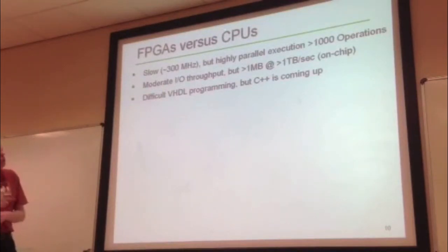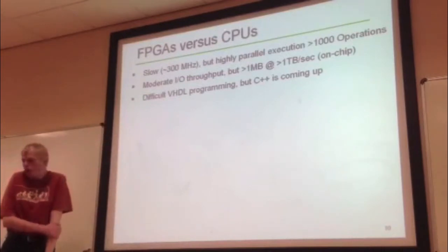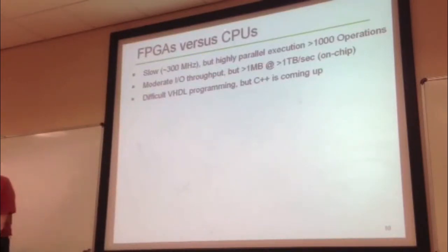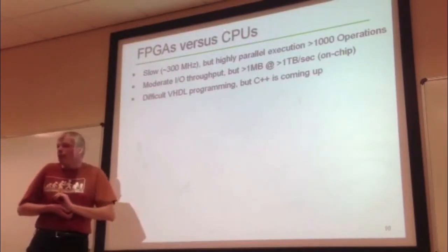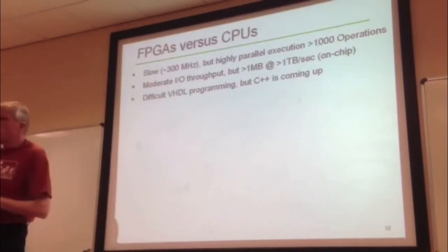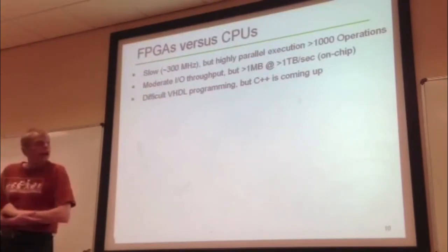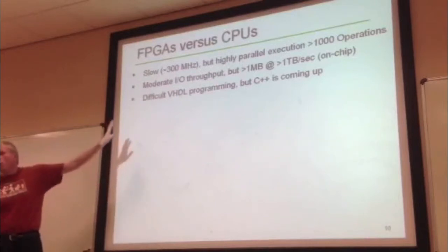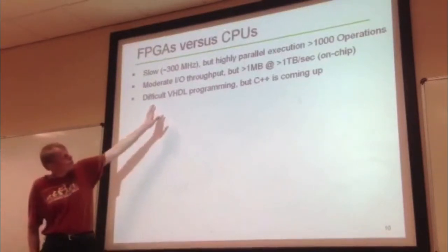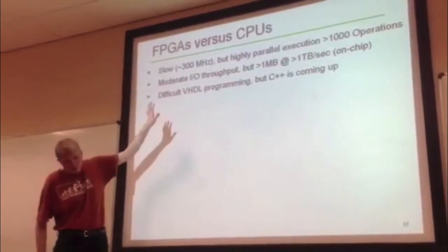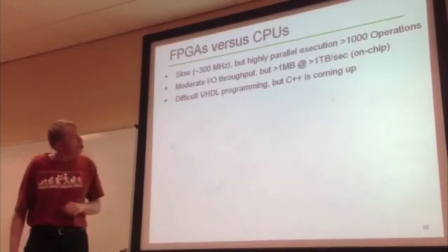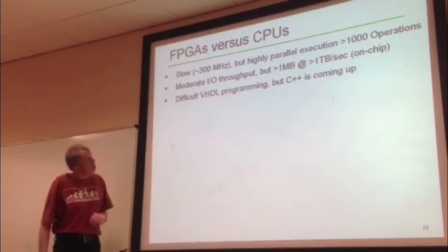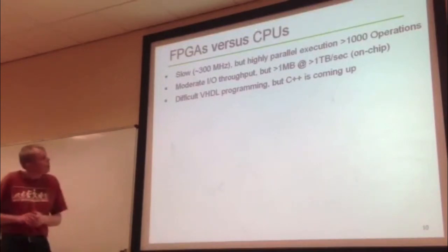These 3 bullets are the most important things you should take away from this, even if you don't continue with FPGAs. The main difference is, an FPGA is rather slow, but it is brutally parallel. Typically you have a couple of thousand instructions running in parallel. So that's the catch. You are an order of magnitude slower with respect to clock speed, but you are several orders of magnitude faster. Typically, for most applications, you get a speedup in the range of 100 times, if the problem fits an FPGA. Not all do.